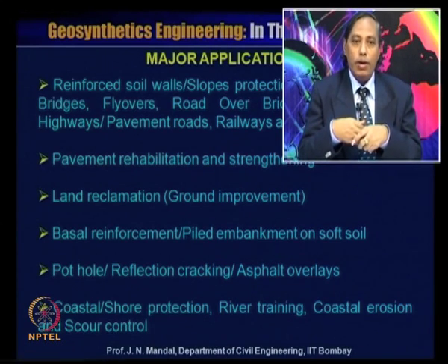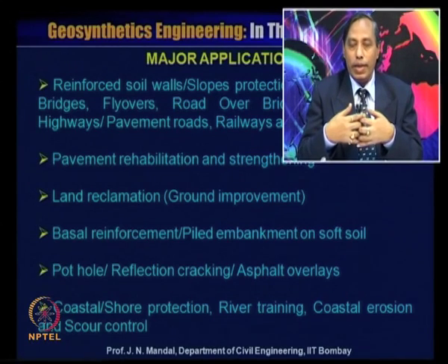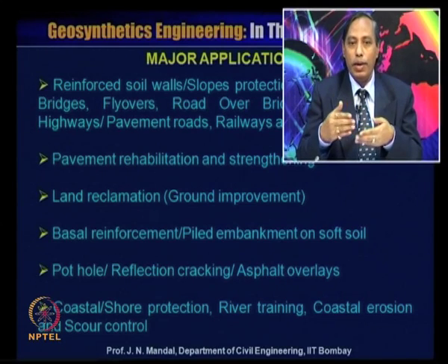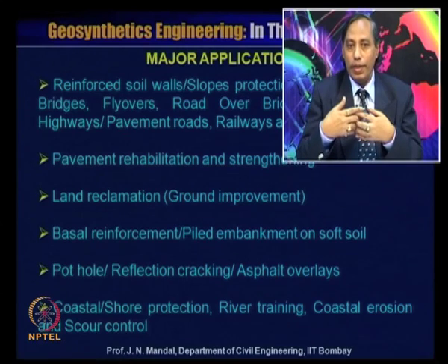You know, there are a lot of potholes, reflection cracking and asphalt overlay. This is regularly going on. After a few months, again and again you keep on providing asphalt on top of the existing pothole. So, we can adopt geosynthetic material to protect against the cracking and the pothole.